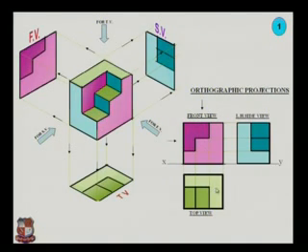If you want to draw the projectors of the top view, then we have to take the 45-degree line from the XY line. Extend the projectors up to the 45-degree inclined line in the horizontal direction, which intersects with the 45-degree line.